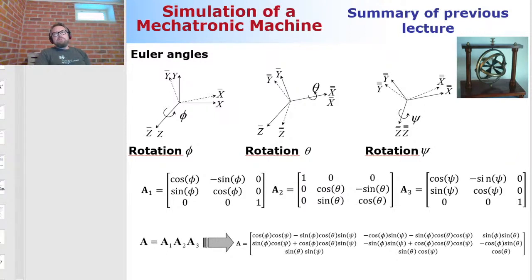Now, how you can do the successive rotations in Euler angles when you're using the rotation sequence Z, X, Z, which by the way is a very often used rotation sequence. Well, you can describe each one of these separate rotations by a 3 by 3 rotation matrix. And this 3 by 3 rotation matrix is the one that tells you where the rotation takes place.